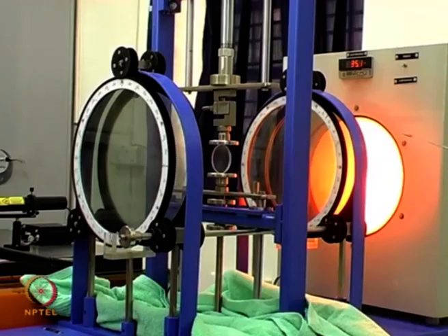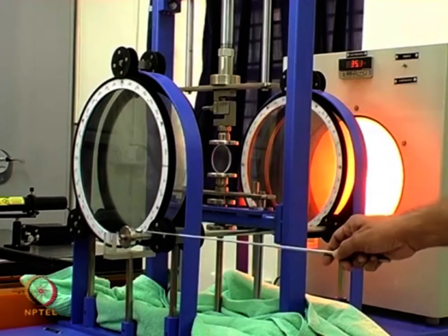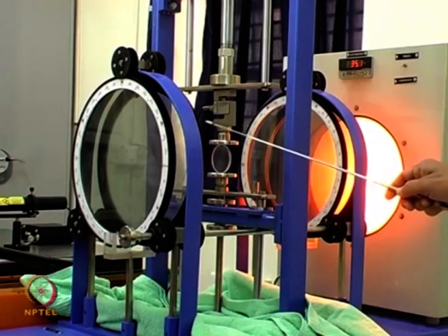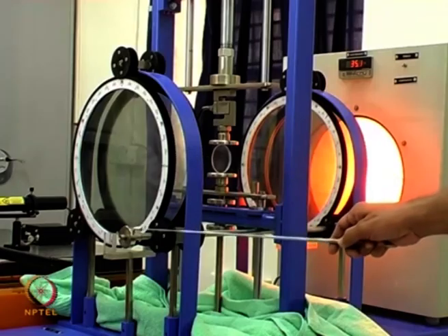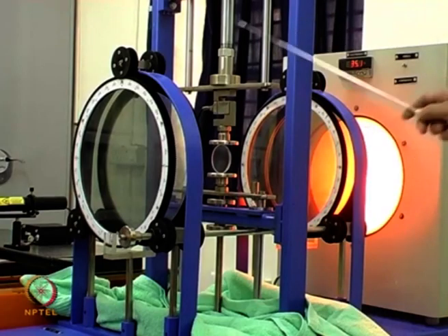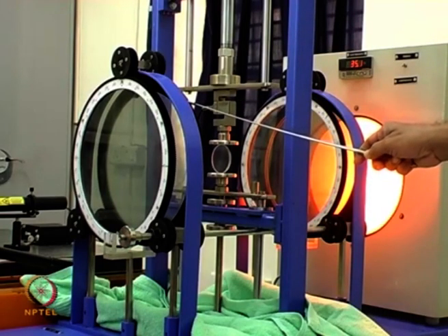All the elements in the polariscope can also be rotated by this knob, and you use this for making this polariscope function as a plane polariscope. In this, you keep the quarter wave plate axis along the polarizer. So, you optically cancel the first quarter wave plate. Similarly, optically cancel the second quarter wave plate.